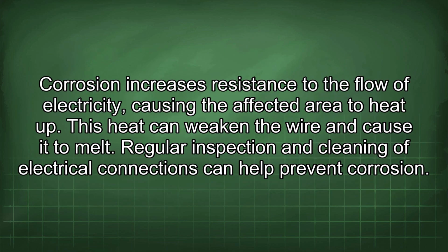Corrosion increases resistance to the flow of electricity, causing the affected area to heat up. This heat can weaken the wire and cause it to melt. Regular inspection and cleaning of electrical connections can help prevent corrosion.